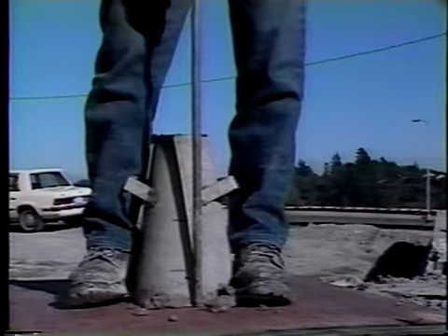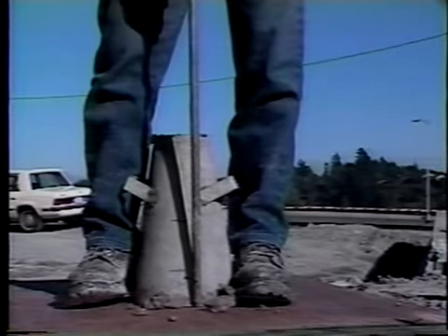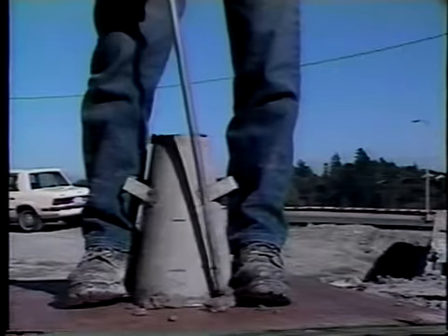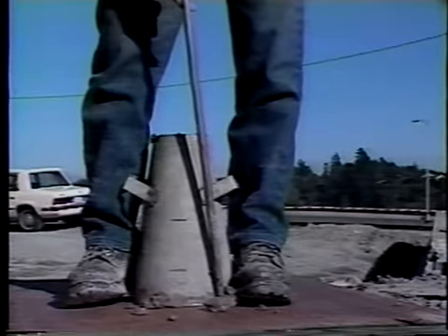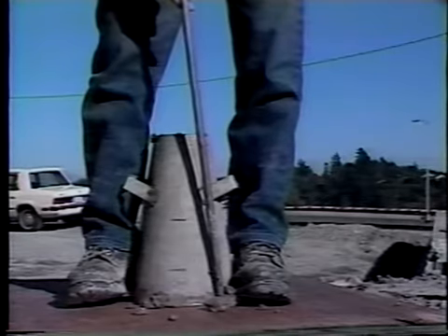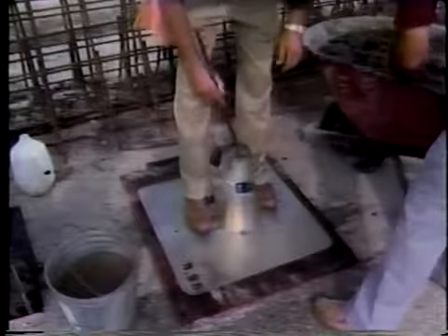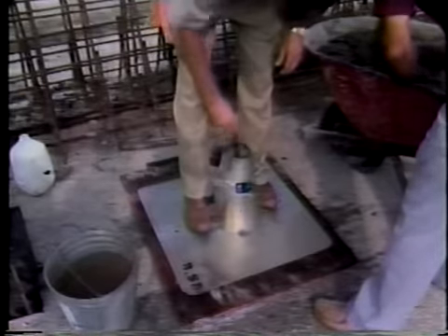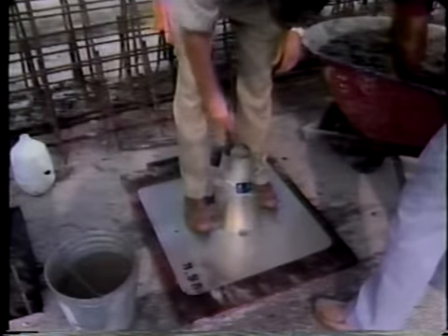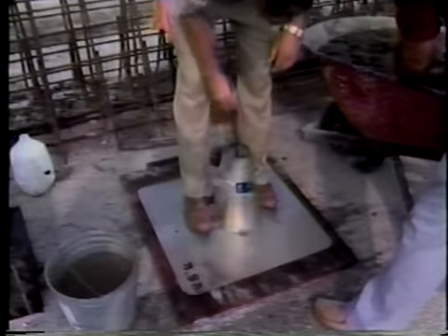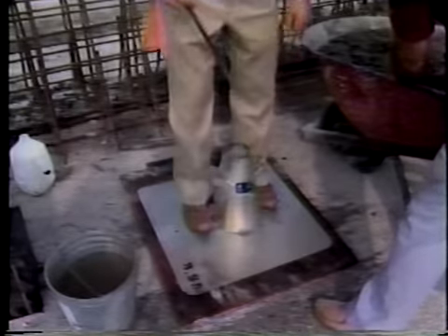Starting at the perimeter, with its rounded tip downward, the rod is inclined slightly to match the slope of the cone. Otherwise, the concrete closest to the cone's sides will not be properly consolidated. The rodding should go to the bottom of this first layer, but just tap the base. Each layer is rodded 25 times, with about half of the strokes made near the perimeter.